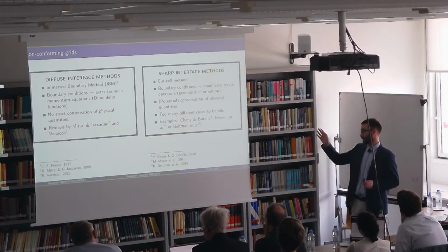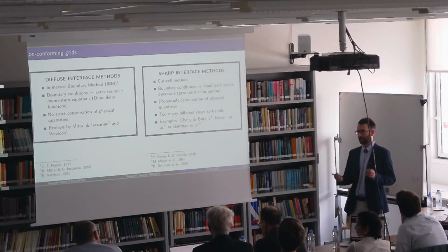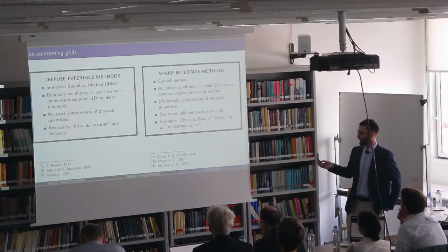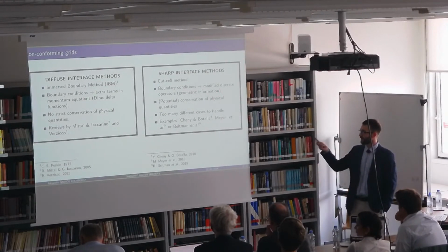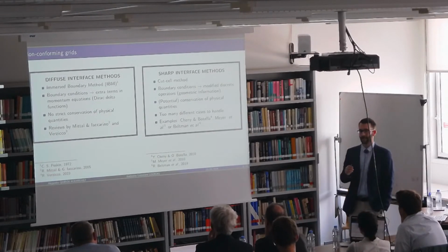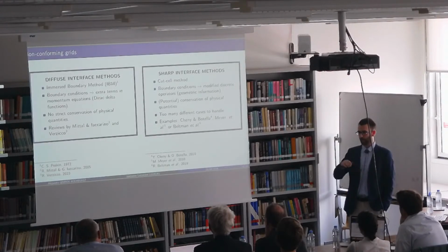The problem, for example, for the cut cell is that there are too many different cell configurations that we have to handle individually, which makes it very difficult to impose the boundary conditions. In the literature, we can find some examples of conservative cut cell methods, but there's not a single cut cell method that is fully three-dimensional, and none of them are used for fluid-fluid interfaces. They're always used for fluid-solid interfaces.